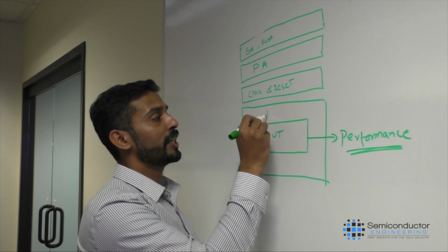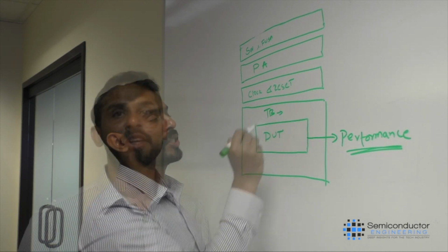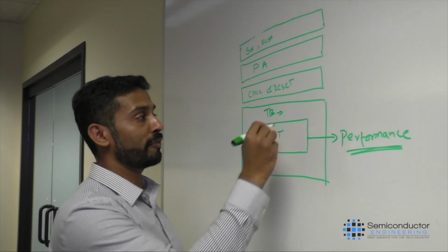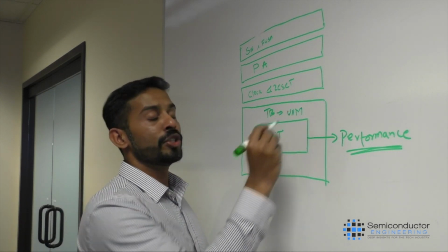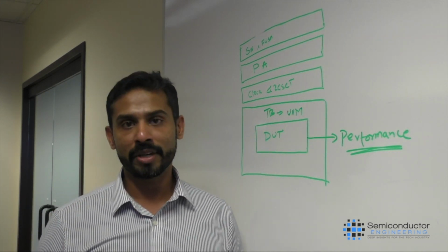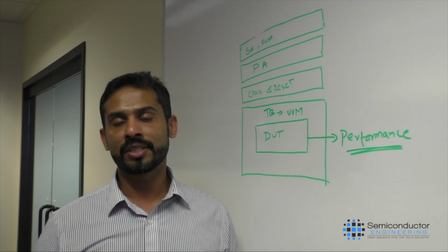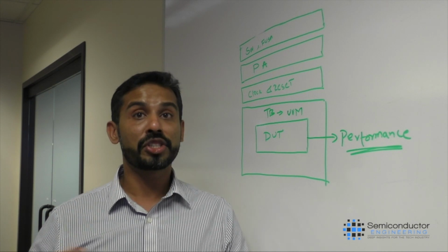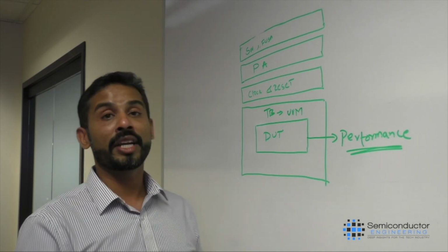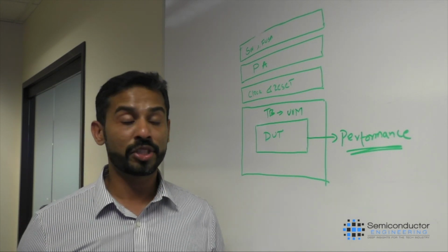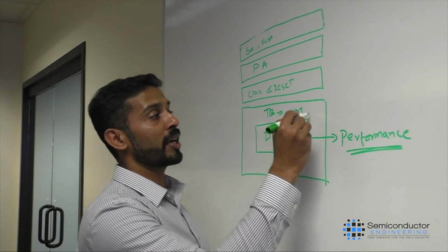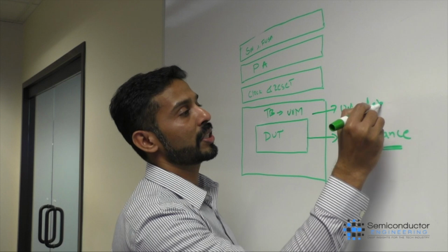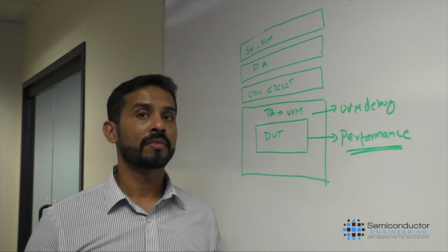Then you have test bench. So industry has consolidated with standard UVM. So you have UVM test benches. UVM is a large software project by itself. Everybody understands that. It's a lot of object-oriented programming. It sometimes is so massive they are bigger than design under test itself. So there's UVM debug that needs to be considered. Big chips also have a lot of dependencies.